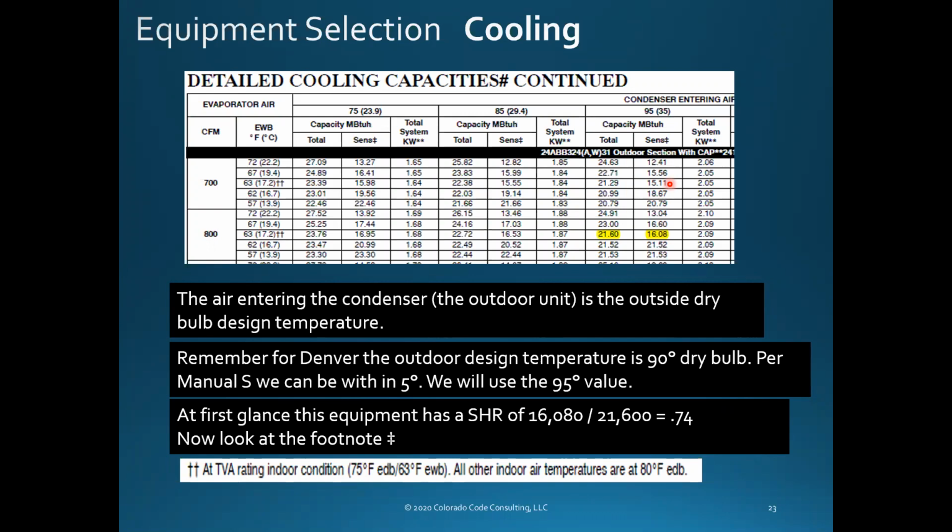If I'm moving less air across the coil, is the coil getting warmer or is it getting colder? It's getting colder, isn't it? Yes. And so now it's going to have more latent capacity because the coil is colder.